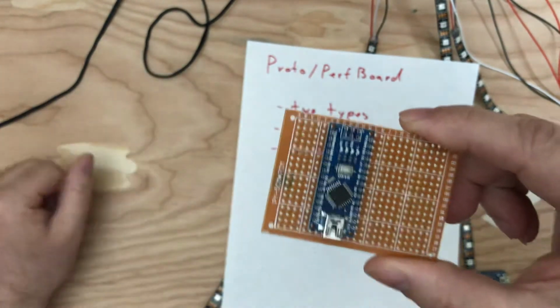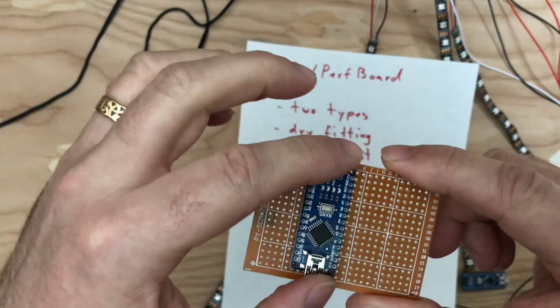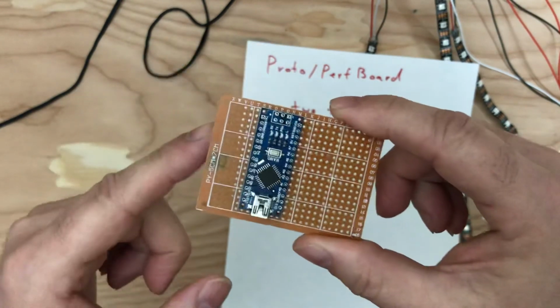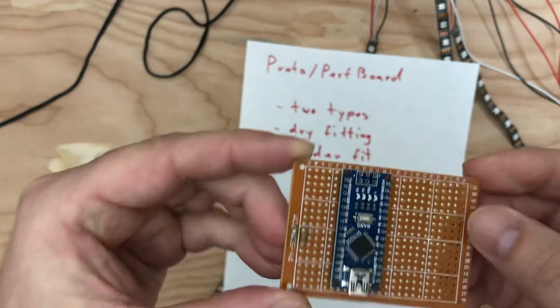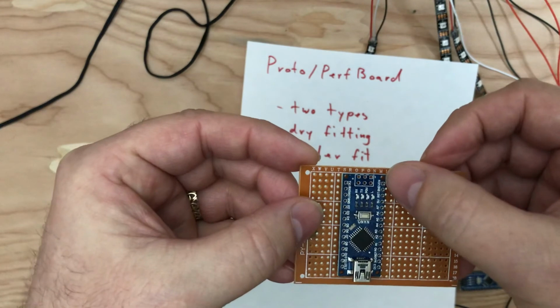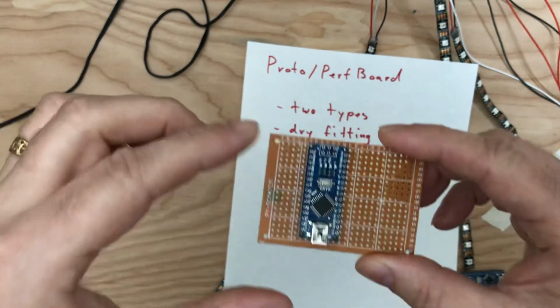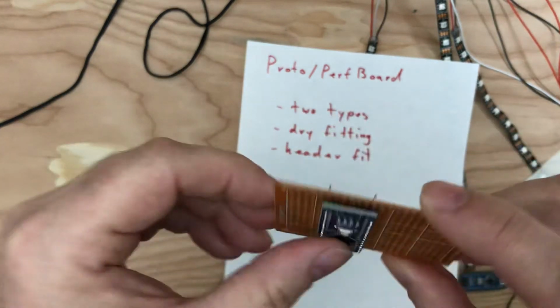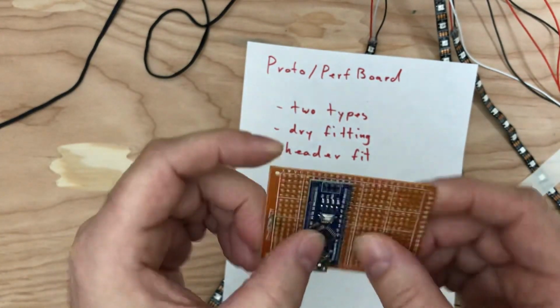Sometimes if you're soldering them on a table or something, there's a chance the pins won't be exactly straight, and if they're not exactly straight, you'll never get it into this board. So what I do is fit it in, put something on two sides, and quickly solder two pins, like one there, and then take it out. Make sure it comes in and out easily and that the pins are exactly straight up and down, or else you're not going to get them onto this board.